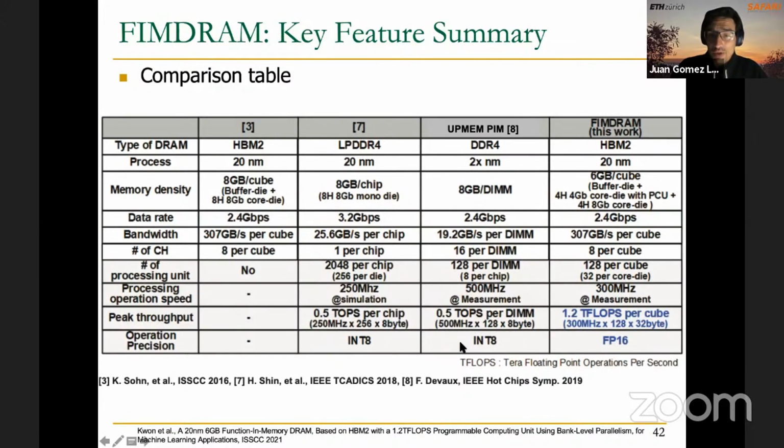But there's still probably the reason why they put here this int8: the only multiplication that the PIM DPU supports natively is for 8-bit integers. Remember that 32-bit multiplications are implemented using a routine that uses repeatedly a shift and add instruction. And probably that's the reason why they put this here. But as I said, PIM supports other data types like 32, 64-bit integers and both single and double precision floating point operands.